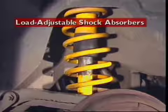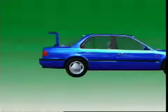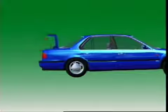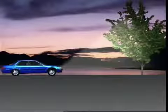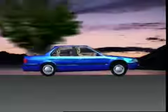This section examines load-adjustable shock absorbers. When vehicles carry heavy loads, their suspension is compressed, causing the rear of the vehicle to be lower than normal. As a result, steering becomes lighter. The alignment of the headlights becomes too high, and the compression length of travel of the suspension over bumps is reduced, causing discomfort to passengers.